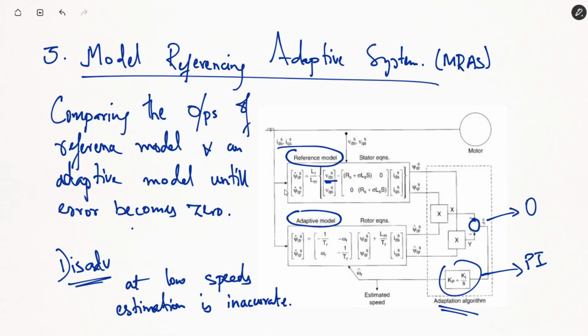What we are doing in this adaptive scheme is estimating the values of fluxes, and from flux values we are deriving the speed values. As already established with the derivative control strategy, the flux estimate is poor with the voltage model at lower speeds, owing to the energy being dissipated mainly across the resistances and a very small amount of energy being used for establishment of flux. So, at lower values of speed, this model will not give us an accurate estimate of speed.